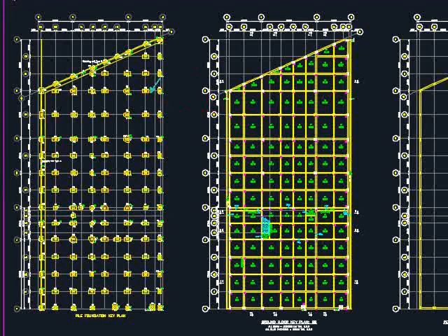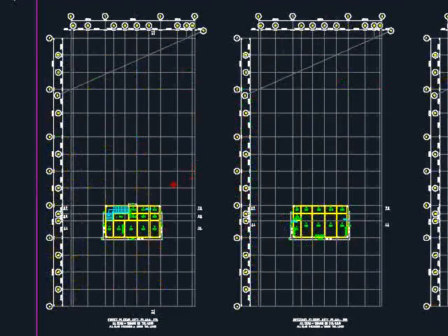It should be reflected in the foundation key plan, the ground floor key plan, the first floor key plan, and so on and so forth. Remember, on every floor, the names of the columns need to be clearly indicated, so that you don't have to flip through different levels of the key plan in order to recognize which column is meant for what.